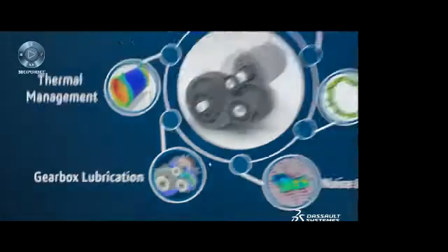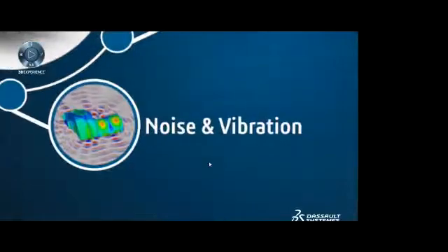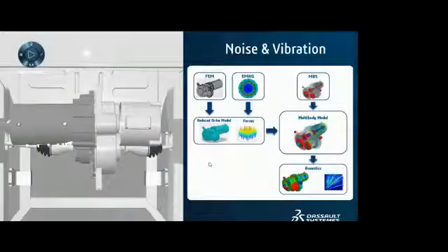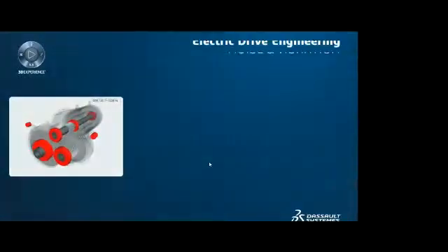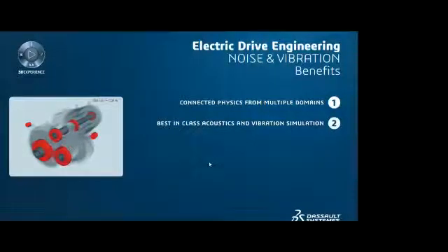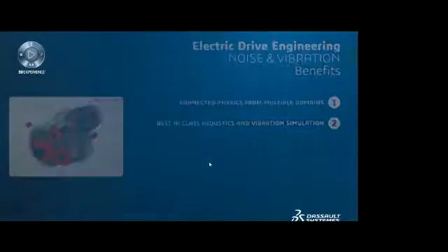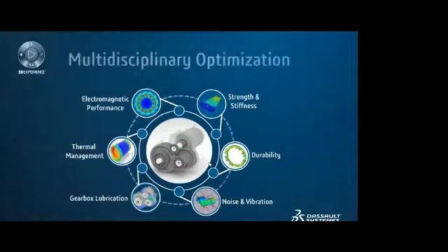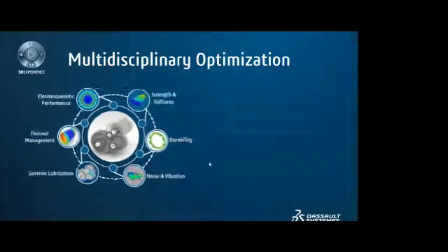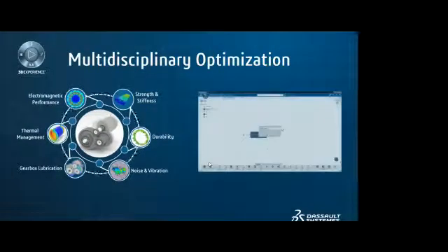The electric machine and gearbox are enclosed in a housing, which must be modeled as a coupled system in a noise and vibration simulation. Simulating and predicting noise and vibration sources and paths, both structure-borne and airborne, is critical to improve overall cabin comfort and component durability. The end design of an electric drive system is the result of compromise between its performance and design requirements, such as cost, allowable design space, and manufacturing constraints.